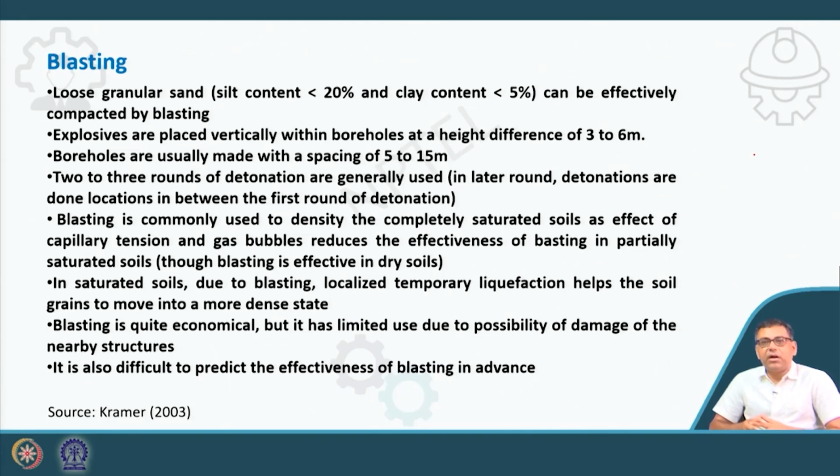Then the third one is blasting. Loose granular sand with silt content less than 20% and clay content less than 5% can be effectively compacted by blasting. That means we have to do an underground blast to densify the soil.